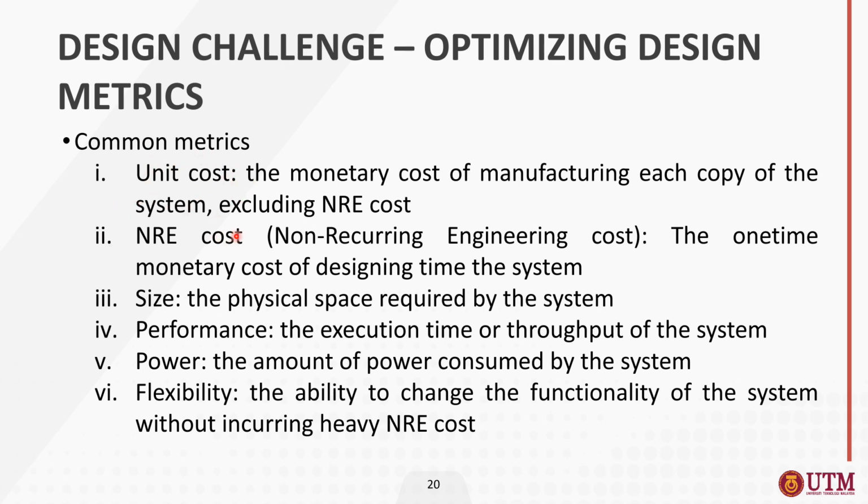If your system requires a very small application, you need to also consider the smaller size of your embedded system. But if your system doesn't require a very high performance embedded system, maybe you can just consider 8-bit or 16-bit of your microcontroller. And then in terms of power, if your system is being installed in remote areas where the power is quite limited, you need to use a microcontroller or an embedded system which is low in power consumption.